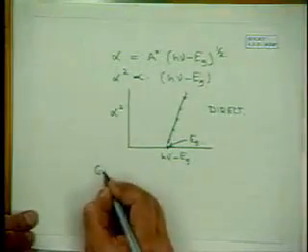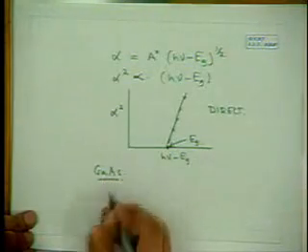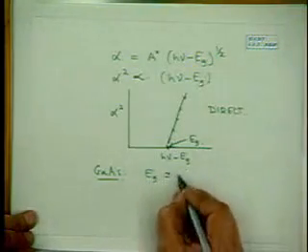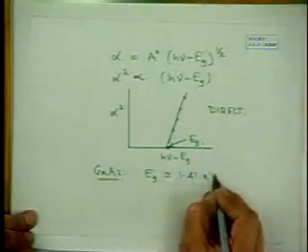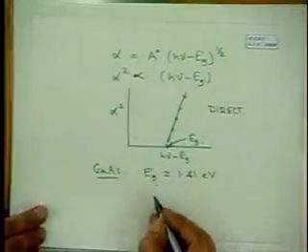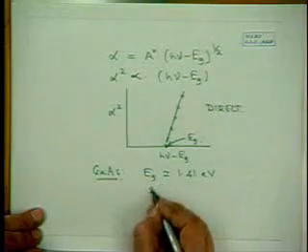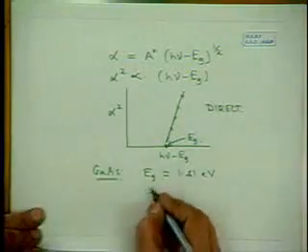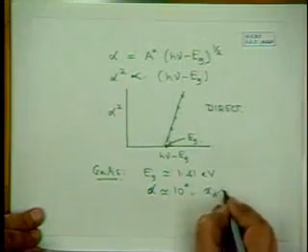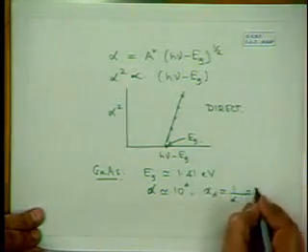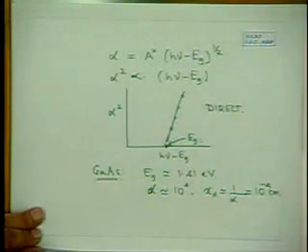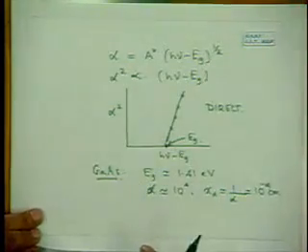So for gallium arsenide, one has a band gap of 1.41 eV, and as discussed earlier, since alpha is of the order of 10⁴, the absorption depth xd is 1 by alpha, which is of the order of 10⁻⁴ centimeter. This is for a direct gap semiconductor.